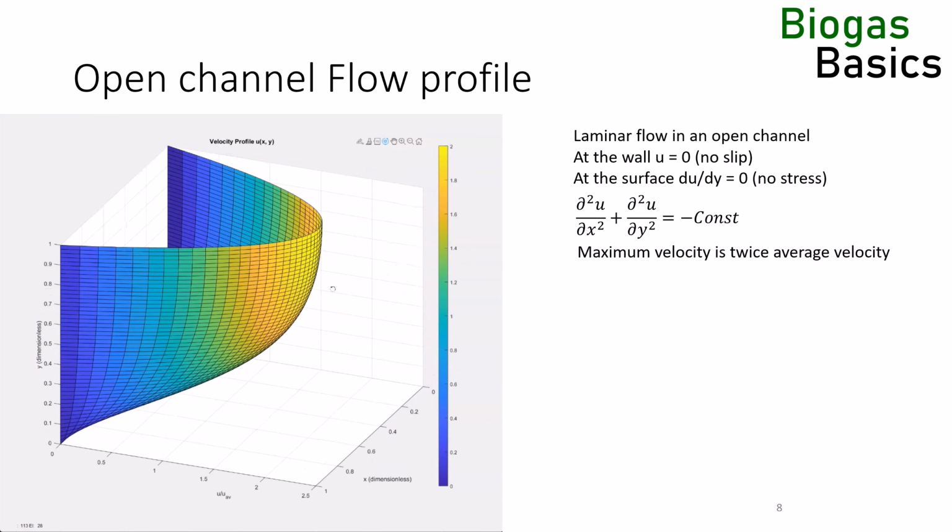At this point, I should mention that technically there is another way to generate a plug flow. A medium of high viscosity and a noticeable shear stress, for example a Bingham-plastic, will form a plug flow in an open channel or a pipe. At high viscosities, these media form a solid plug in the middle of the flow. Here the shear is below the yield stress of the fluid, and the fluid behaves like a solid.